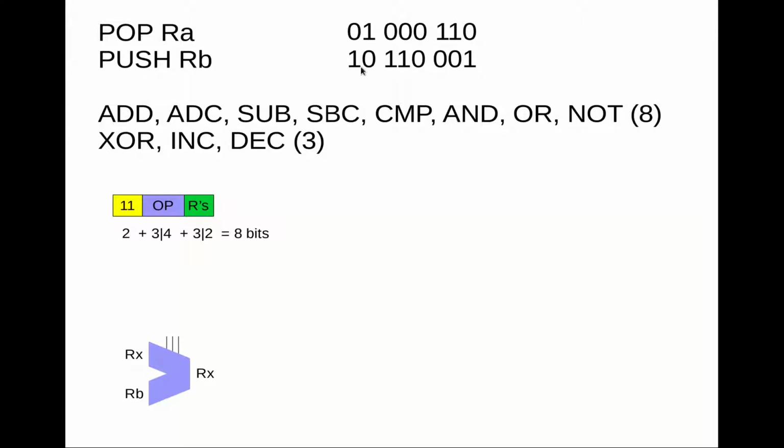And so that way these instructions don't really need to fit into that scheme. So the fact that we can't directly address the stack pointer in this case, that's fine, because this instruction is not encoded using that scheme at all. It's encoded using the load and the store scheme, which we looked at in the last episode.